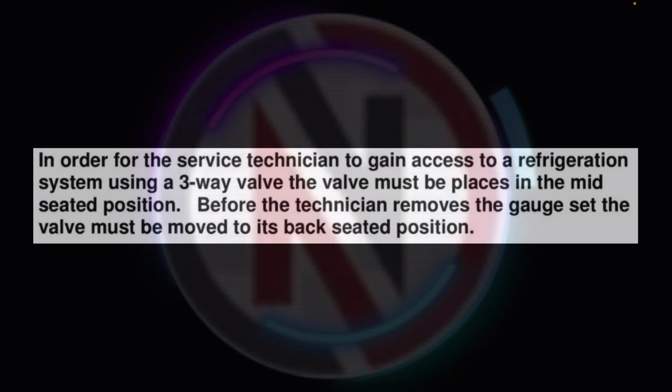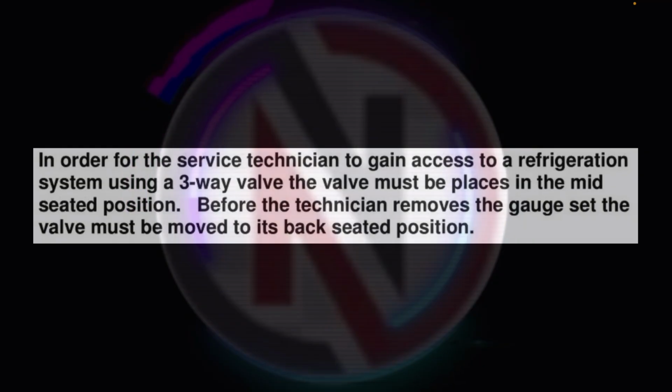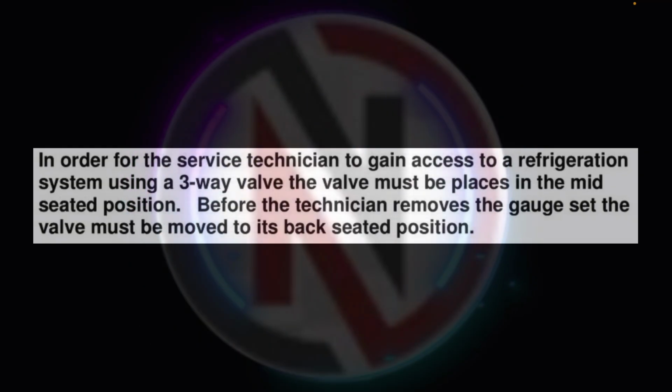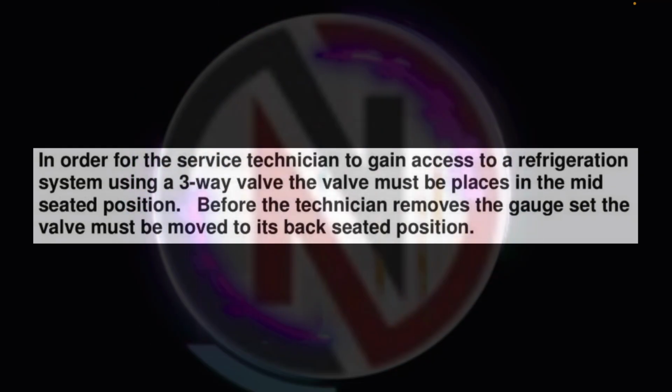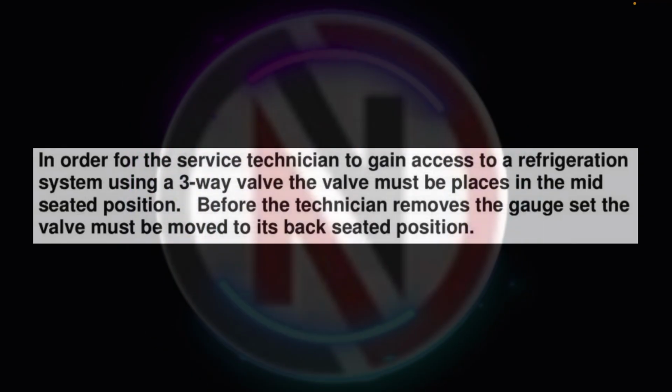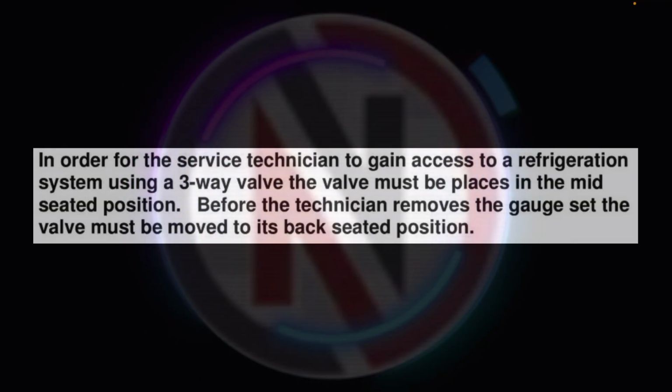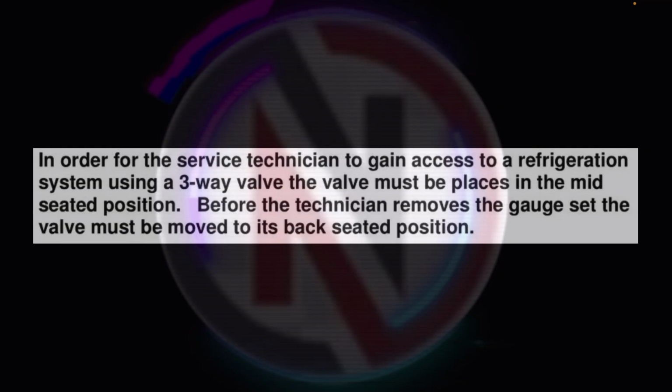In order for the service technician to gain access to a refrigeration system using a three-way valve, the valve must be placed in the mid-seated position. Before the technician removes the gauge set, the valve must be moved to its back-seated position.